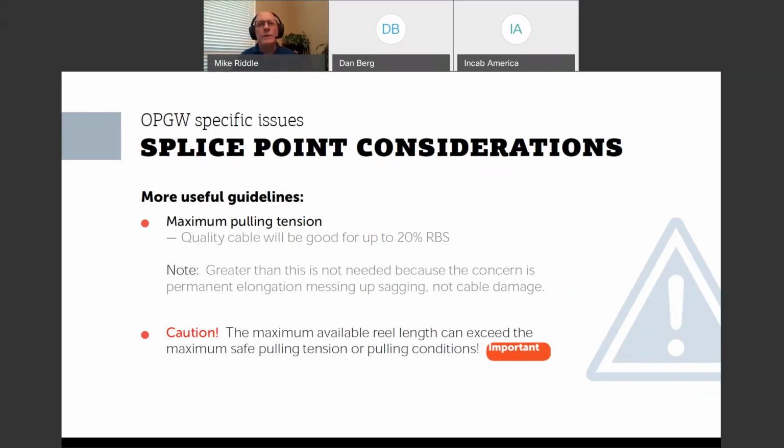I'm just setting up a condition where I can either get the sag right, but the tension is wrong, and specifically it's higher than you designed it to be, or I can get the tension correct, but the sag is wrong, and specifically it's greater than what you designed it to be. So you need to ensure that this pulling tension is going to be less than this limit so that your design is installed the way it was designed.